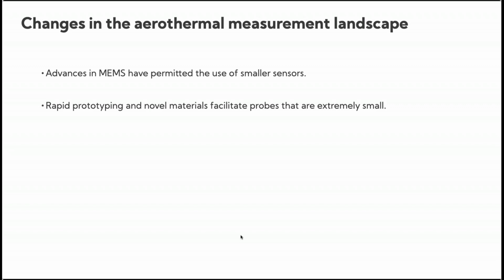So from the perspective of, say, gas turbines, that effectively means you can run your experiments much faster rather than waiting, because there'll be a certain lag between when you actually reach a certain temperature and when your sensor measures that temperature. And by placing the sensor closer to the actual probe head, you're able to increase the frequency response, thus accelerating the pace of your experiments.